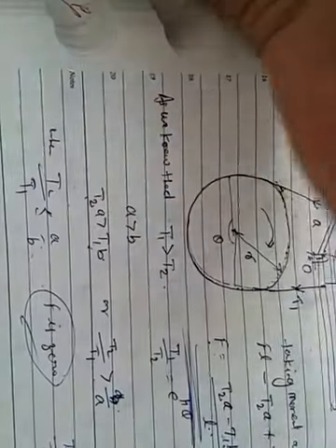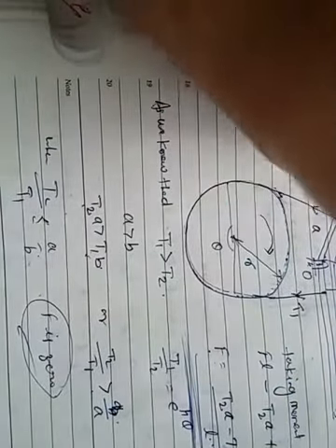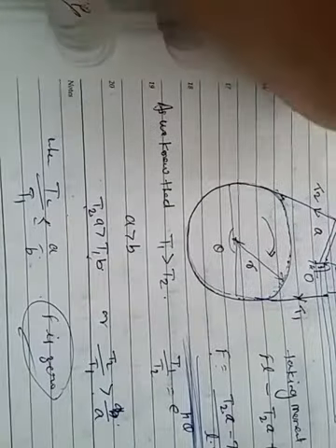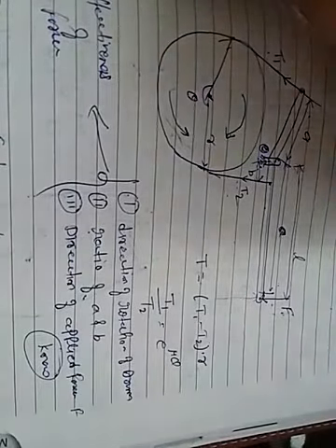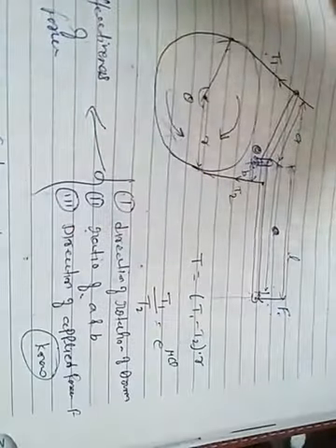So finally, the conclusion we have added here is that the effectiveness of the force depends on these three statements I have written here: the direction of the rotation of the drum, the ratio of A and B, and the direction of the applied force. So this is the first case.